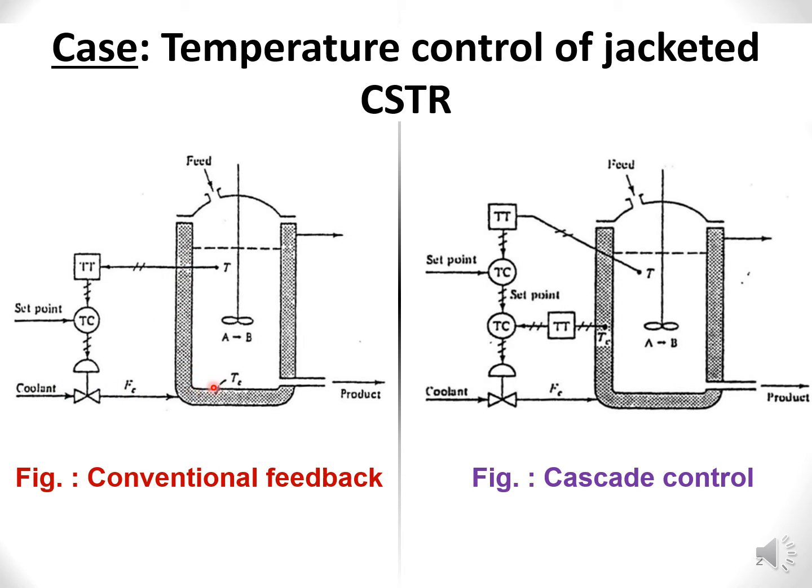So if we have the set point for the temperature of the product or the reactor, the inside and outside is the same, we will be measuring that, and the set point is going to be the set point for the coolant flow. So we can see that the effect is actually controlling the temperature but manipulating the coolant flow.